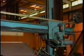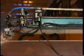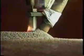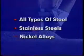Equipment includes automatic wire feed devices and joint tracking systems to move either the welding head or the workpiece. Submerged arc welding is commonly used to join all types of steel, stainless steels, and nickel alloys.